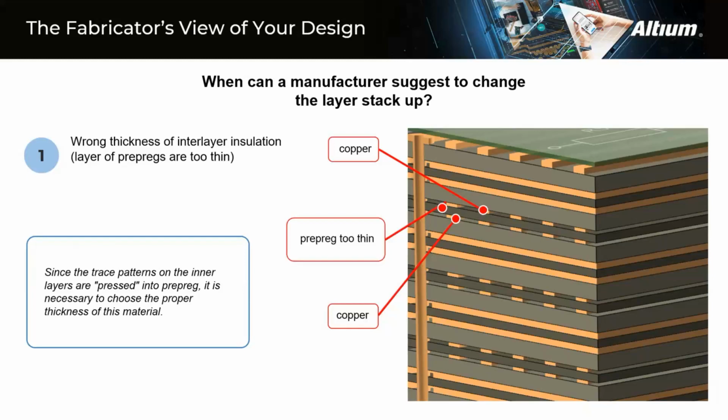Here, usually to overcome the required thickness of the board, as a designer, we used to decrease the thickness of the dielectric material or decrease the thickness of the copper, which will be resulting in the abnormal shape of the stack up, which will not be fabricatable by the fabricator. Then in that case, we have to carefully review the stack up, or you can take the inputs from the fabricator.